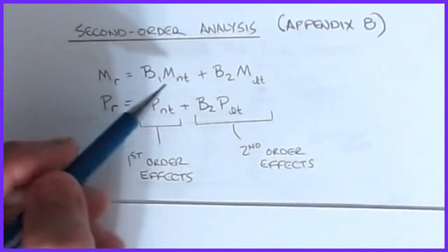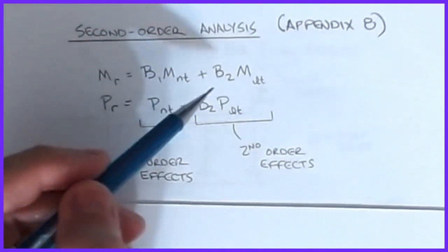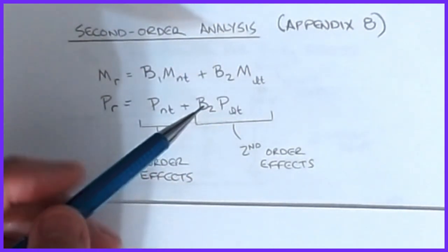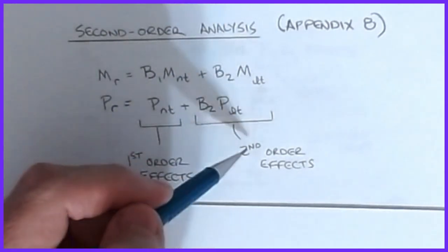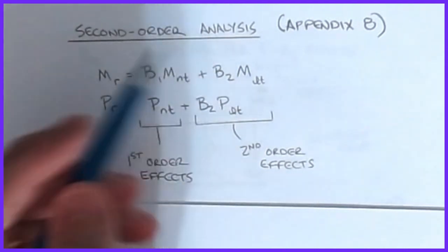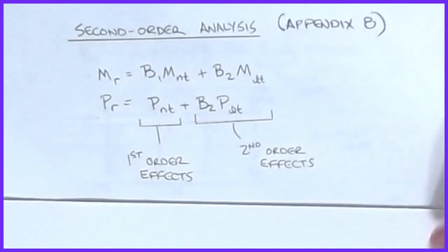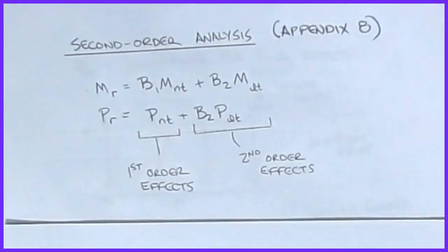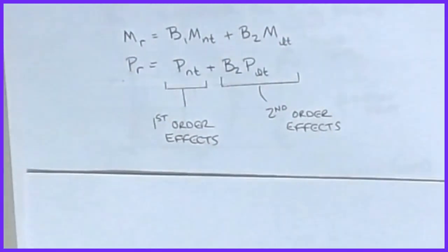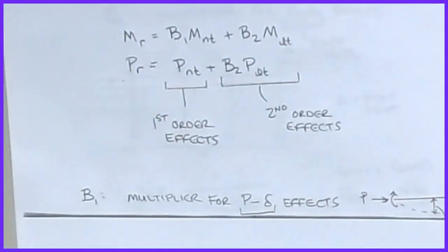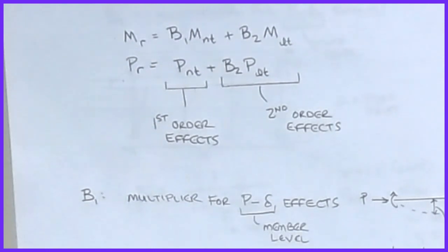Okay. The B1 is a coefficient. I'll explain that here in a second. And then B2 is another coefficient that's related to the lateral effects. These lateral effects are the second order effects that we talked about. As the column drifts over, the load causes an increase in moment. These are those increases. Okay. So we've got to be able to separate those. So the analysis is already getting a whole lot more complex, because again, as you change the size, the deflections change, and as the deflections change, the moments change, and that changes your size. And again, it's this huge circular problem, all right?